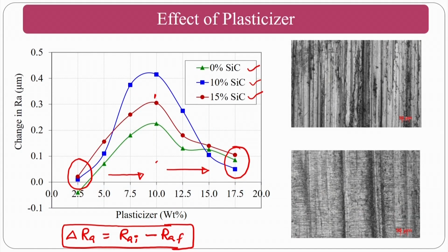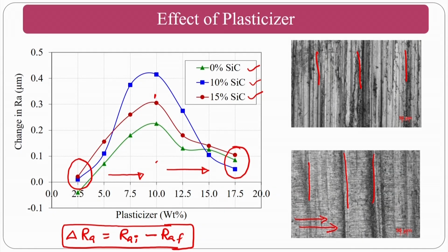As you can see, these are the grinding marks and the medium just flows on top of them rather than shearing. That is why you can see dominating lines here and very, very small marks of abrasive flow finishing here. Instead of abrading the surface, it simply flows because you have too much of this plasticizer.